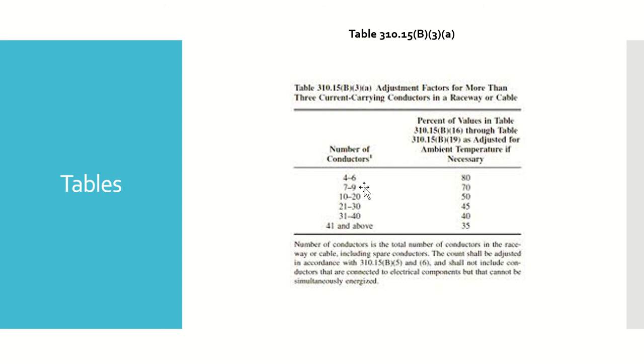This is one of the reasons why we don't want to jam our conduits full of wires, is because they're not able to dissipate that heat when we've got a lot of current flowing on them. And over time, that heat wears on that jacket, and that jacket becomes brittle and breaks away. So, next time you guys are pulling wire, make sure that you're paying attention to how many conductors are inside of that pipe, because you could significantly be affecting the allowable ampacity of that wire.